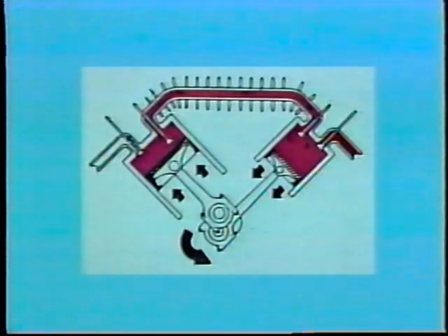During the travel time through the intercooler, the compressed air is cooled either by air or water that passes over the intercooler. So when it reaches the second stage, much of the heat from the first compression has been dissipated. And since the air is now cooler, more of it can fit into a given space. Therefore, the cylinder in the second stage can be smaller than the first stage.